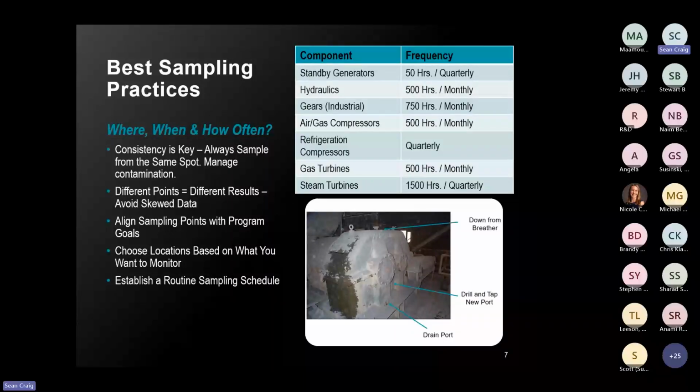You should also ask yourself, what specifically do you want to monitor? Is it the overall performance of the system, or the condition of something, like the pumps? Are they wearing out prematurely? Are the filters getting clogged too soon? Or maybe it's a sample just to see the state of the bearings inside my system, or the babbitt wear on my very old gearbox.